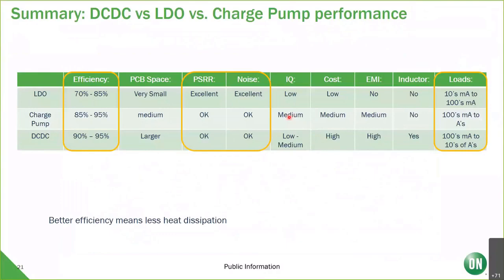And then finally, to summarize, and I really recommend hanging on to this particular slide. This is a nice summary. I look at LDOs, charge pumps, and DC to DCs, compare their efficiency, the space, power supply rejection, and noise. I group those together. The loads that they service.